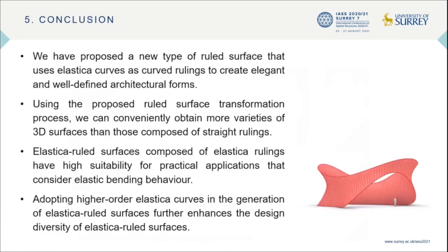To conclude, we have proposed a new type of ruled surface that uses elastica curves as curved rulings to create elegant and well-defined architecture forms. Using the proposed ruled surface transformation process, we can conveniently obtain more varieties of 3D surfaces than those composed of straight rulings. Elastica-ruled surfaces composed of elastica rulings have high suitability for practical applications that consider elastic bending behavior. Adopting higher-order elastica curves in the generation of elastica-ruled surfaces further enhances the design diversity of elastica-ruled surfaces.